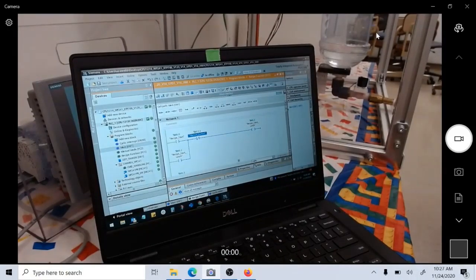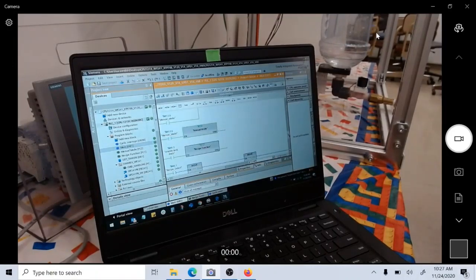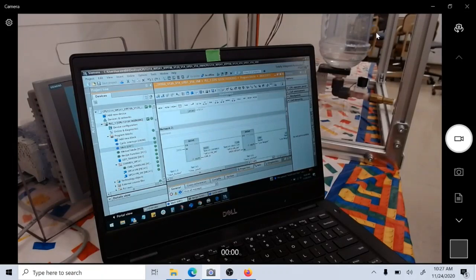So to show everyone the code and the program here on OB1, in order to operate and to report the value of the load cell from the scale module, a value of 230 must be moved into the command B, which is part of the cyclic interrupt.